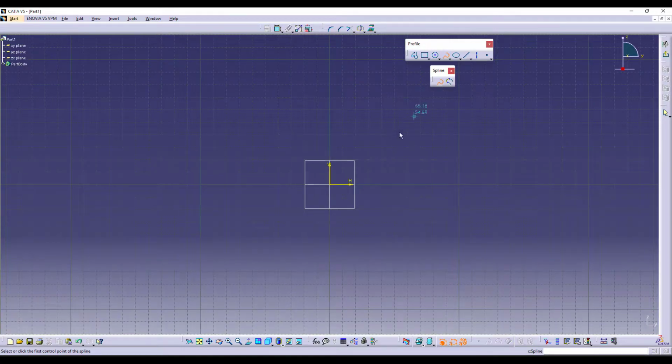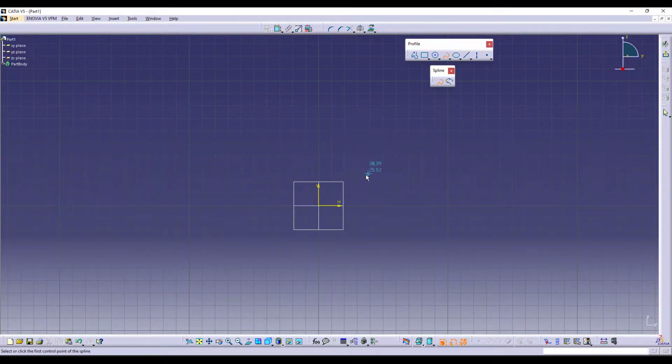When you click on the spline button, you can keep using your left click to keep moving and create the shape you desire. Again, escape will exit the command. Since you have not constrained it, you can just left click on the selected node and start moving it wherever you like. This is either called a node or a control point.